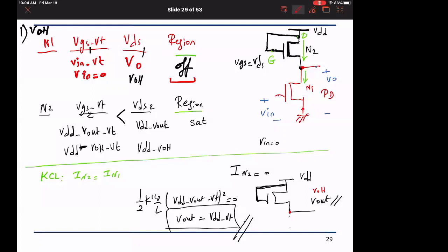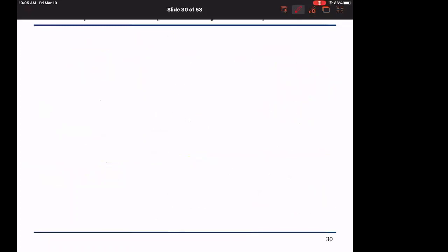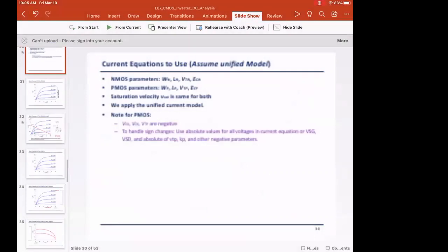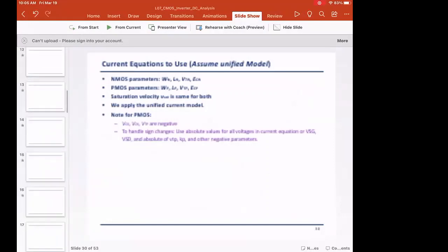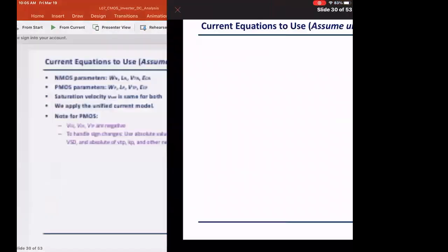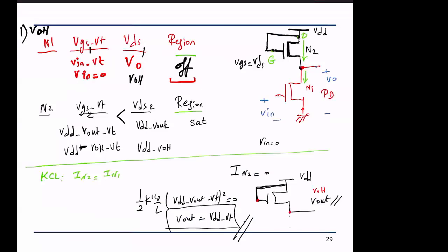Okay, so we said last time that if I have the NMOS charging a node, it cannot pull it up strongly all the way to VDD. It will pull it up to VDD minus VT if the input gate is VDD as well. For the same circuit, I can find the other points in a similar fashion. For the same circuit that I have here, I can also find the other points.